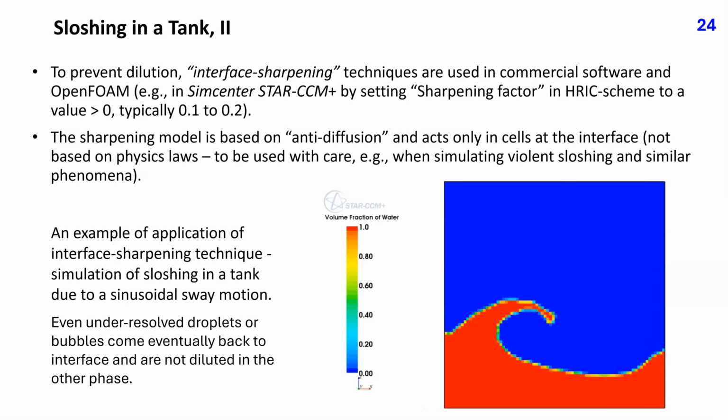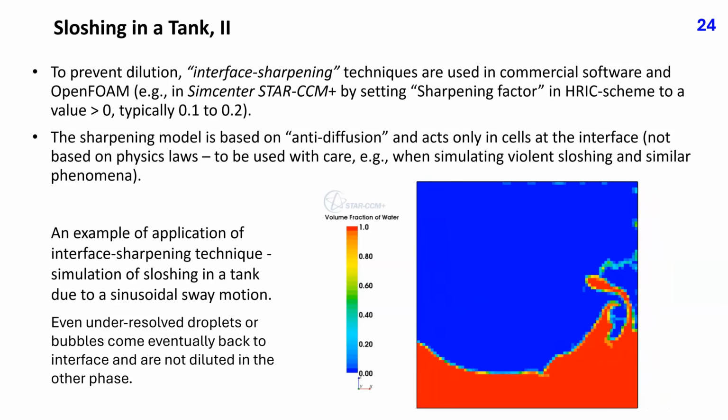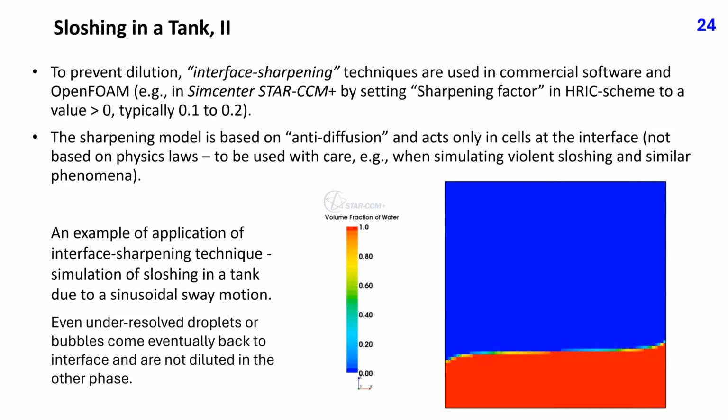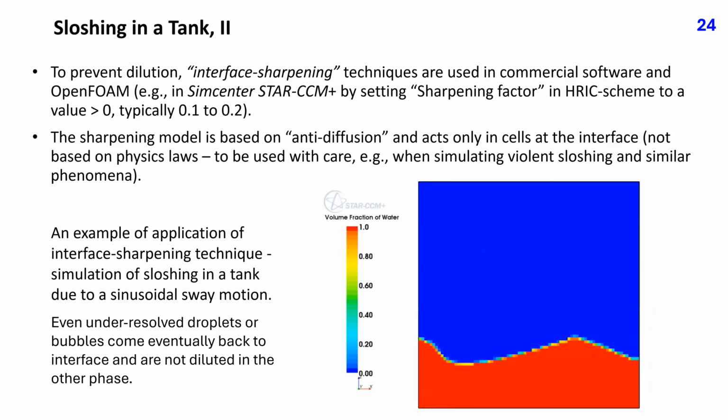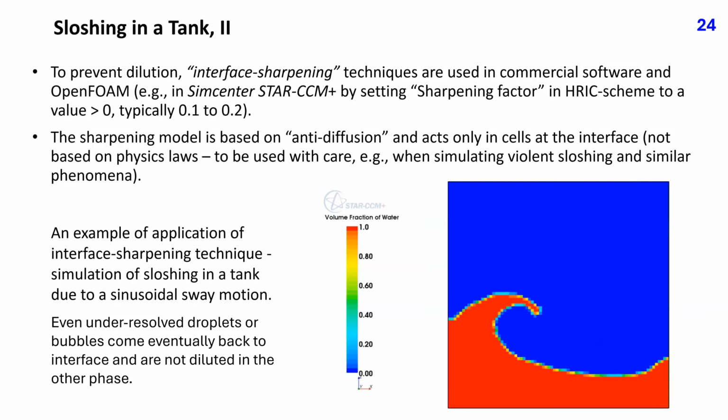This model is not based on physics laws. It is designed to avoid interface smearing and should be used with care. It is appropriate to activate this feature when simulating violent sloshing and similar phenomena. An example of an application is shown in this video.